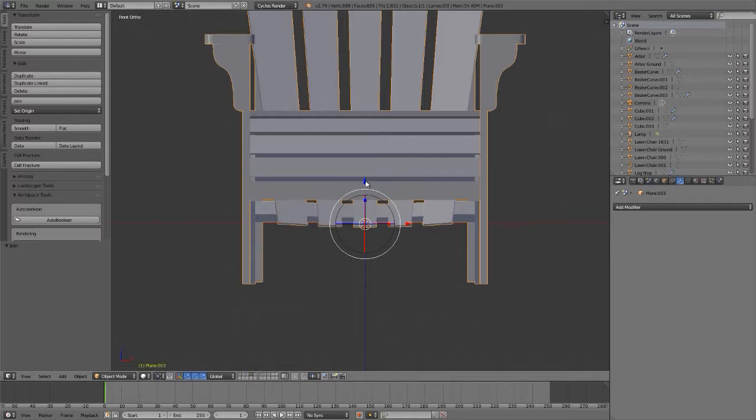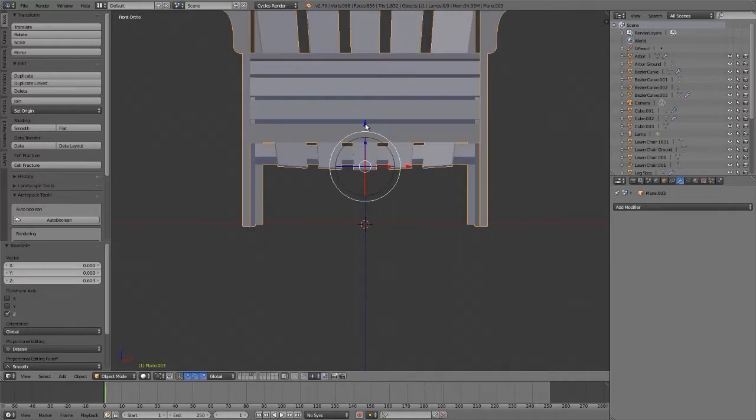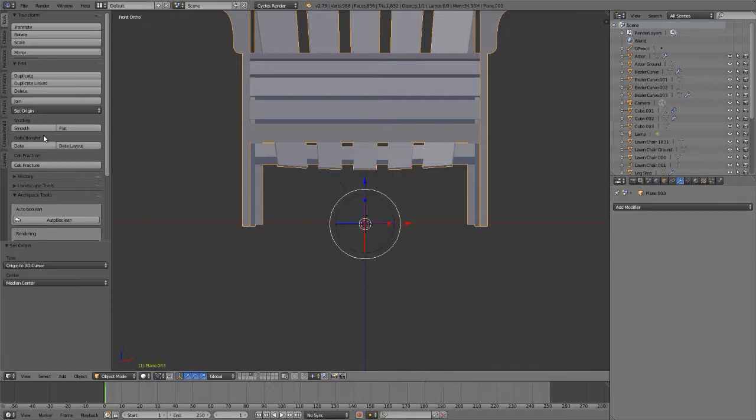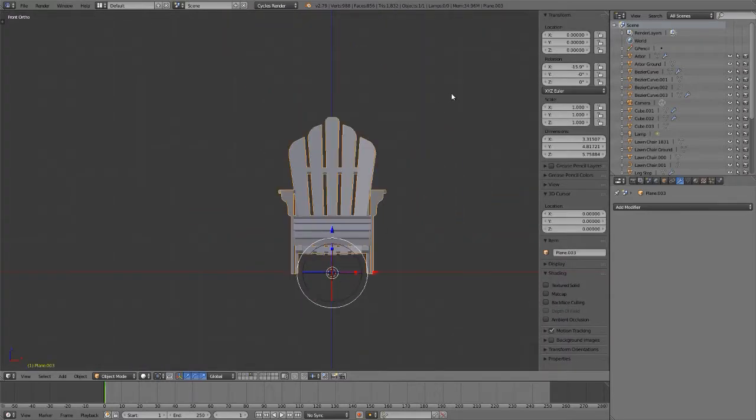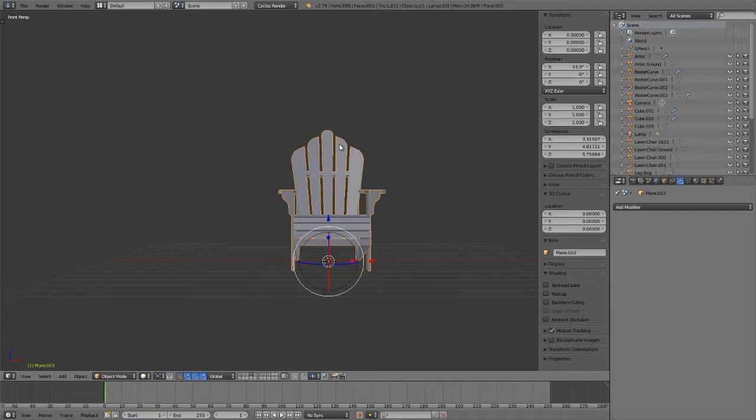And now, set the origin to the 3D cursor, which I hope you've left at origin. In the properties, we've maintained the rotation because my final selection happened to have been the part I rotated. So Control A and apply rotation. And now that 15 point whatever is gone, lost to history.